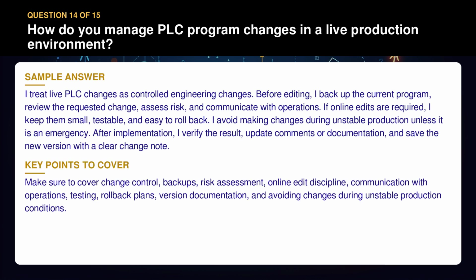Make sure to cover change control, backups, risk assessment, online edit discipline, communication with operations, testing, rollback plans, version documentation, and avoiding changes during unstable production conditions.